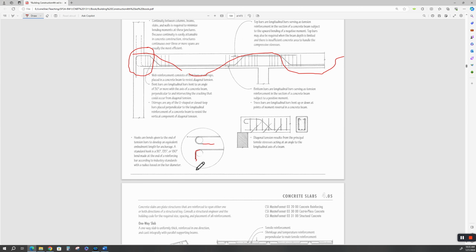And it does, because what actually gives you your strength in your concrete is your embedment length. So if I had a block of reinforced concrete and I just stuck in a single rebar, I'd have to stick it way down in there. But if I put a hook on that rebar and formed it like that, then I wouldn't have to stick it down so deep.